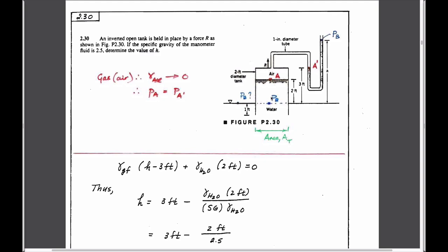And as the bucket's pulled out of the water, you can imagine that if you put your thumb across this exit for the bucket, you'd expect to get a suction on it as it comes out. And so that's really what's going on here. This suction is measured in the manometer, which originally you presume starts off horizontal but modifies itself to adjust to the new pressure regime in here.